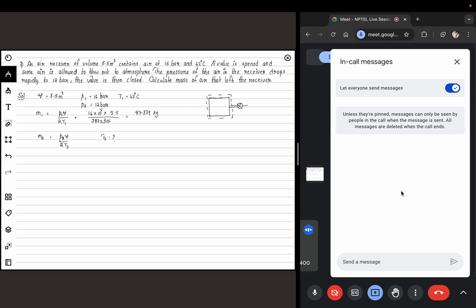So what can I do about it? Again, you start with your equation Q dot minus W dot is d(U)cv/dt plus H out minus H in. I'm just writing out and in. We are neglecting the changes in kinetic energy and potential energy.